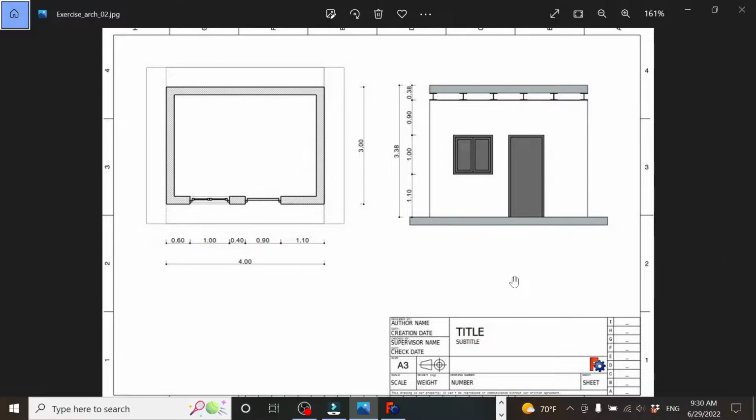On our blueprint we can see a massive slab which is underground, below zero. This is our zero, our slab below zero level. As you can see, we don't have any dimensions on the blueprint, so we can reasonably play with sizes. Our house is 4 by 3. This is our slab right here. So let's create a 5 by 4 slab with a height of 0.2 meters.